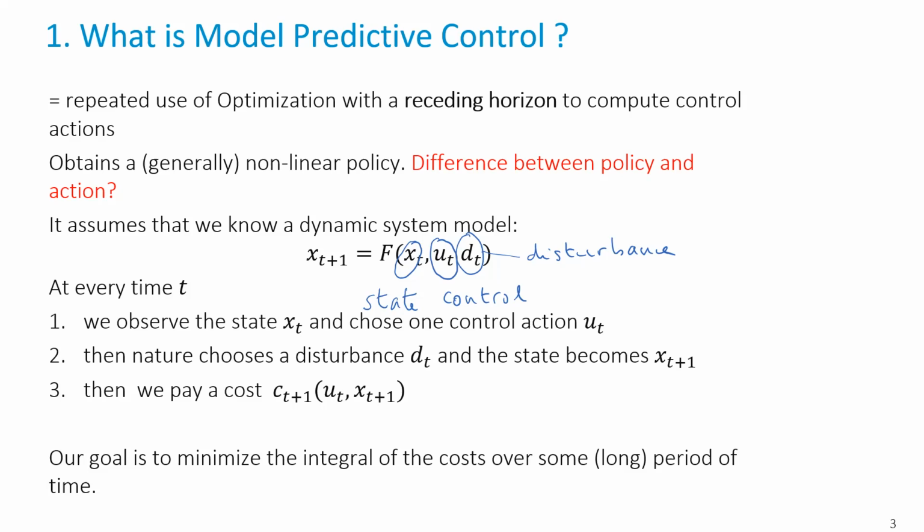In the context of a smart grid, we had seen that the set points of the generators could be computed in advance, or instead what we could compute in advance is the parameters of a linear controller, and that led to what is called affine control feedback. We will see a different technique to address the same goal, and this technique will lead to an implicit control.